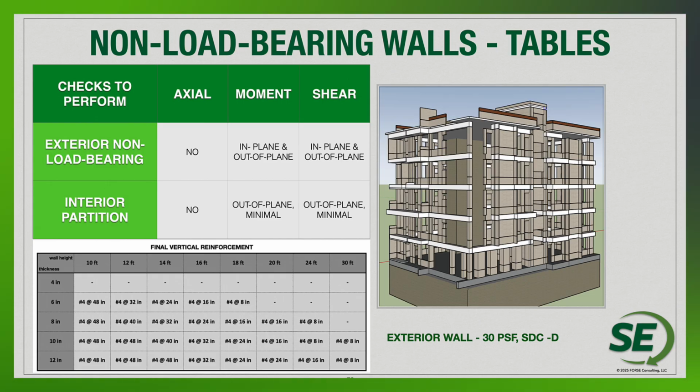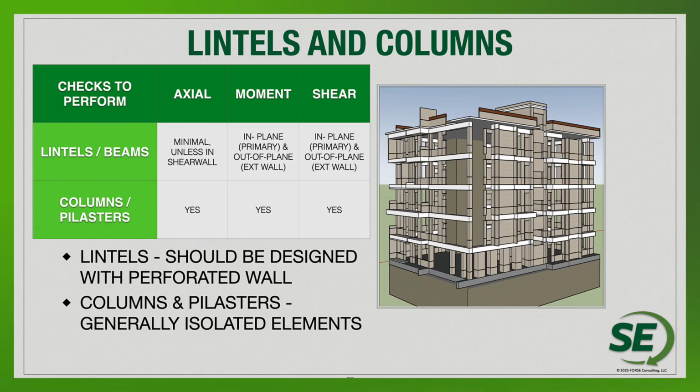If we look at lintels and beams, really there's going to be minimal axial force here. We're really kind of stuck with designing that section primarily for bending, for both the in-plane and out-of-plane direction, making sure that we have moment and shear capacities. Again, the benefit for lintels is we certainly can add overall depth to the design, increase the section, which certainly helps with the overall analysis and design.